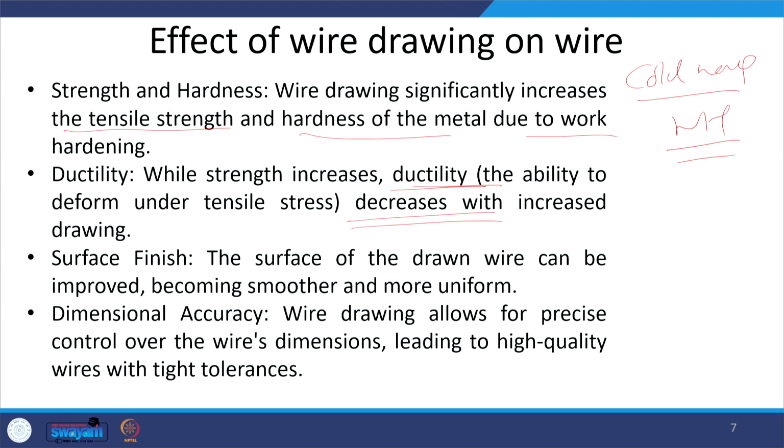So, the greater the reduction realized through wire drawing, the greater will be the increase in strength and the greater will be the drop in ductility.